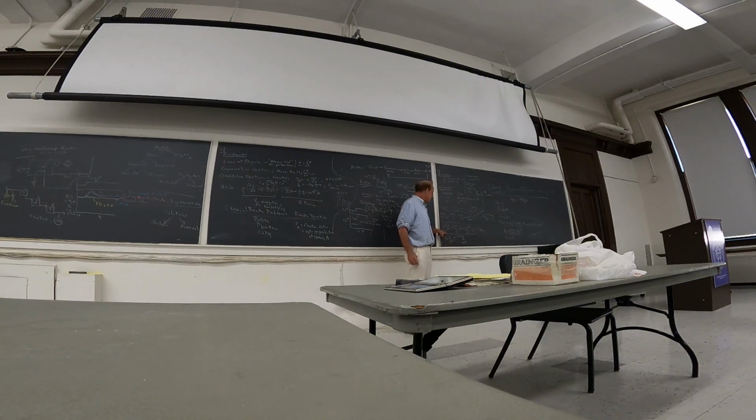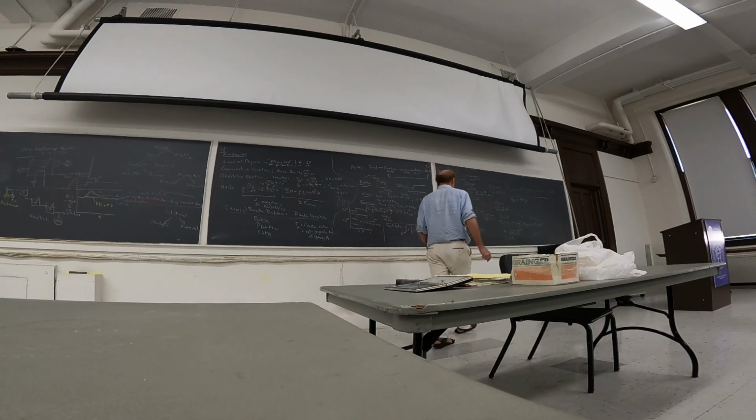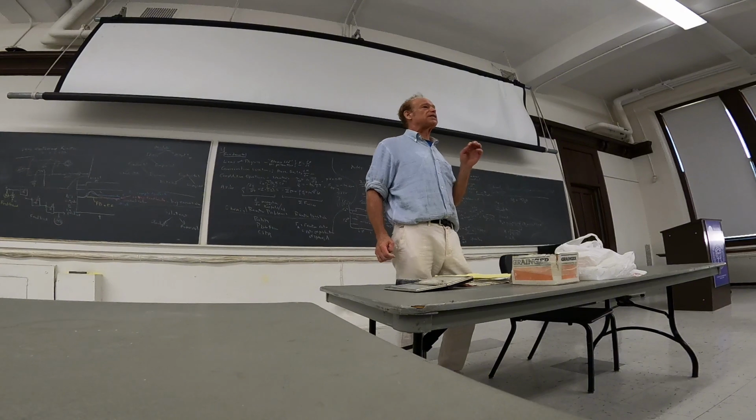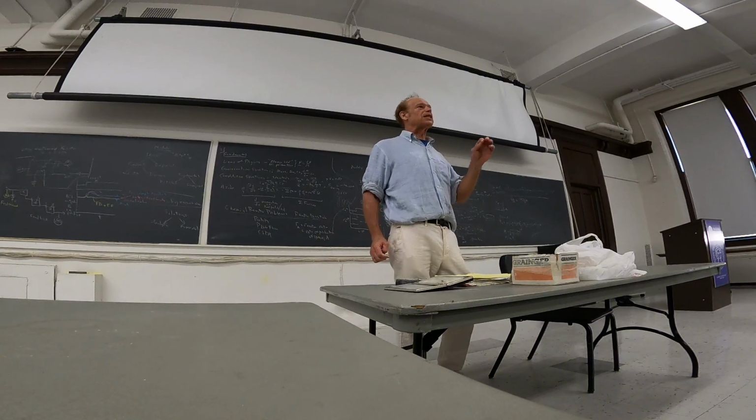So tau is units of time. Tau is often called, it's an unfortunate name, space-time. It has nothing to do with relativity. Tau is the amount of time it takes to replace one fluid volume in the reactor.